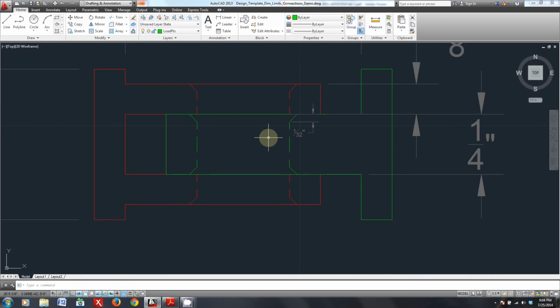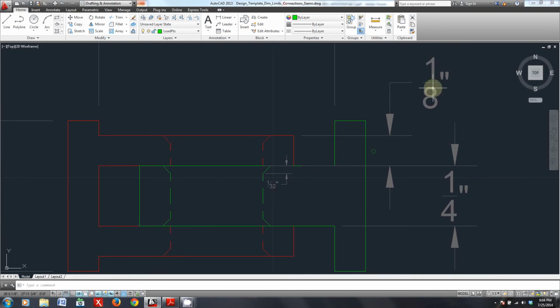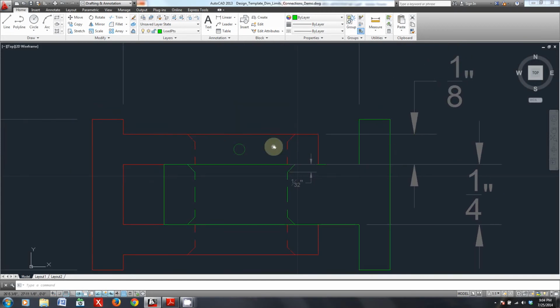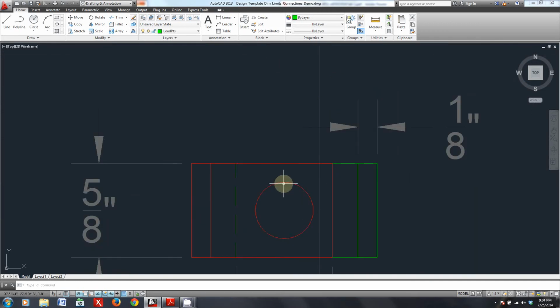So now we know more or less what these should be, and I've just chosen some kind of characteristic length scale or dimension. In this case, I'm borrowing this 1/8 inch thickness on our female wing, and I'm using that to inform this: I'll just make this clearance 1/8 inch, and likewise, I'll make this clearance 1/8 of an inch. Easy peasy.